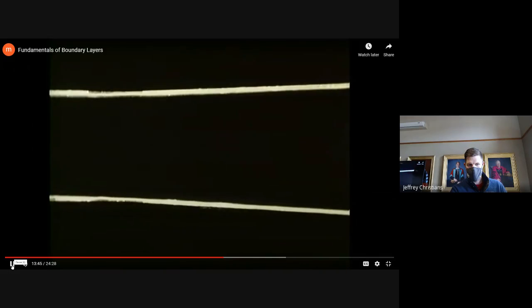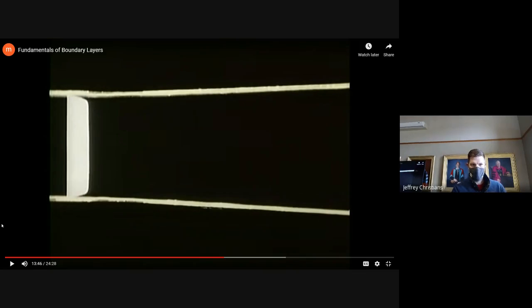On the other hand, in the divergent channel, instead of contracting, it's diverging from thin to relatively wider. So what's happening to pressure? It's decreasing from left to right. So what kind of force is that applying on our fluid? It's applying a force from right to left. Pressure is pushing against our fluid flow, pushing from right to left, causing our flow to slow down.